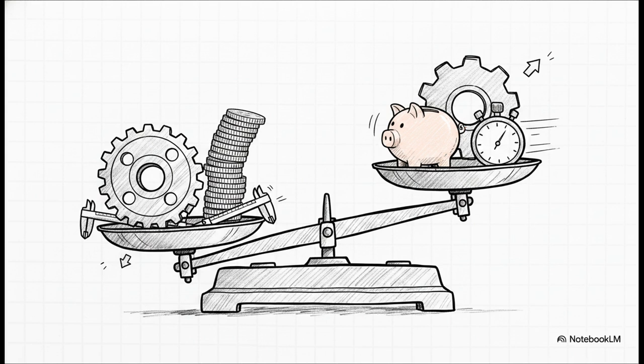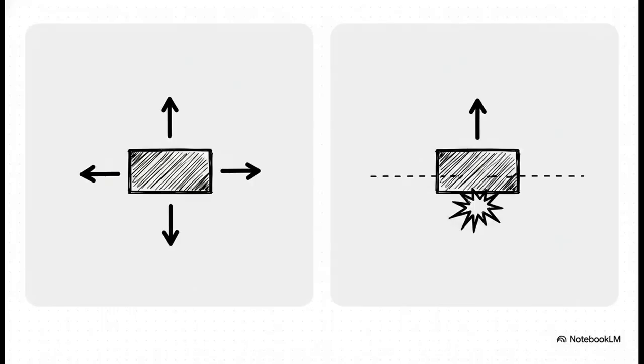But this final point is absolutely crucial: controlling costs. Why not just try to make everything as perfect as possible? Because tighter tolerances require incredibly expensive, high-precision machinery and way slower production speeds. Wider tolerances are simply much cheaper to produce. An engineer always has to balance safety and function against the real-world realities of a manufacturing budget. Engineers typically map out these tolerances in two different ways.